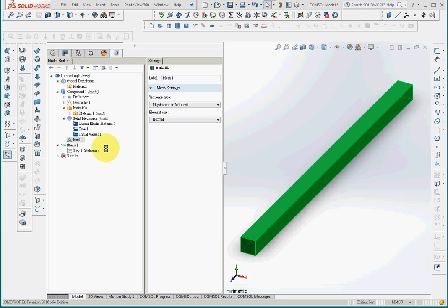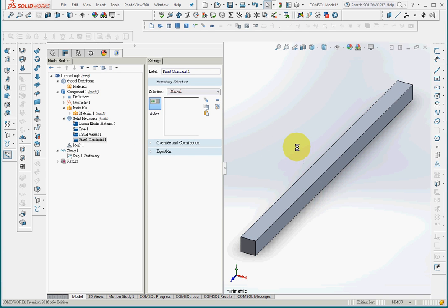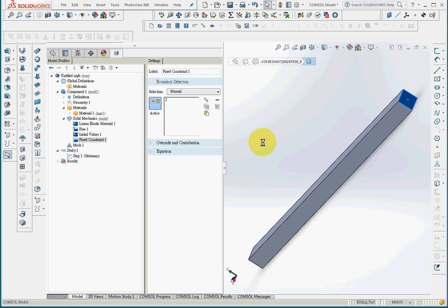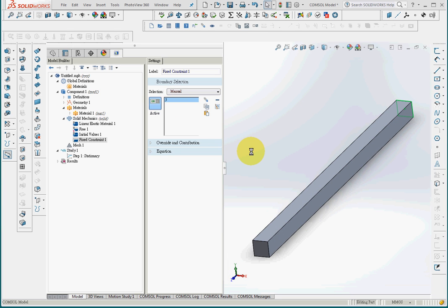And the third step is to generate mesh, and I'll choose a finer mesh and build. And this is the mesh that I've got. For the fourth step, I need to apply boundary conditions and loading. So I'll choose fixed constraint and choose this area as the constraint. And there's no confirming step or confirming function in COMSOL. For example, in ANSYS, you need to apply the process, but in COMSOL, there's no such process. But you have to be very careful that make sure that this item is here, so that the constraint is